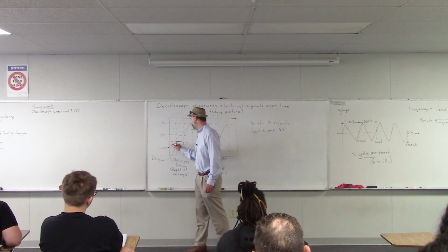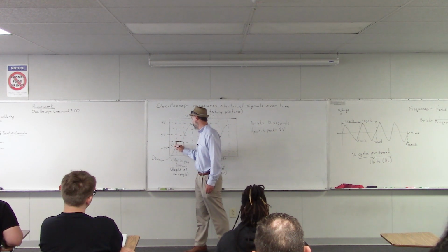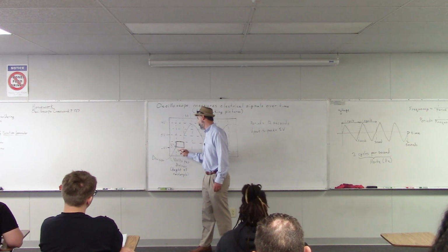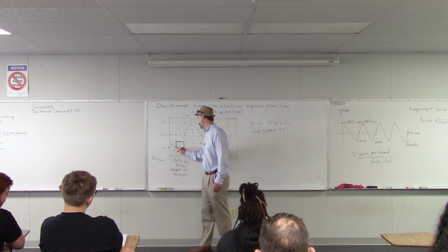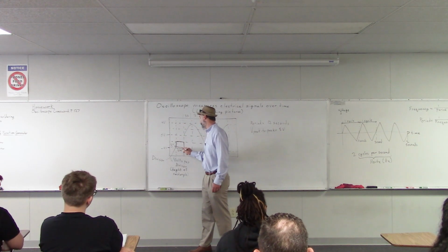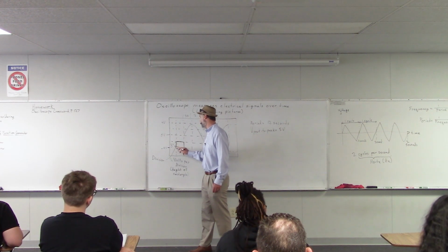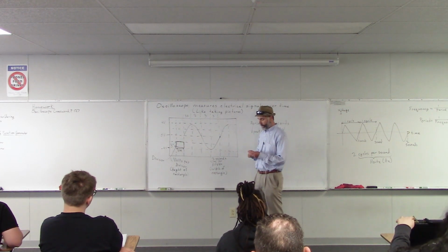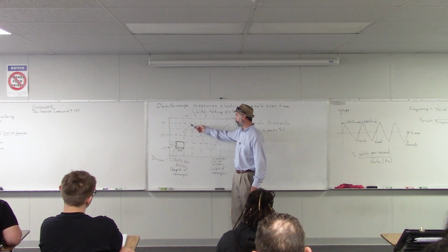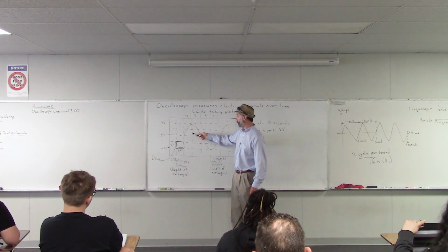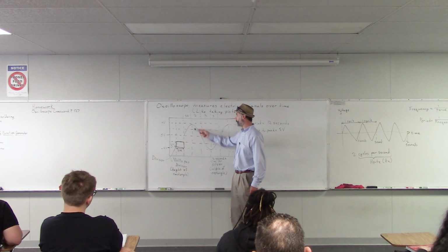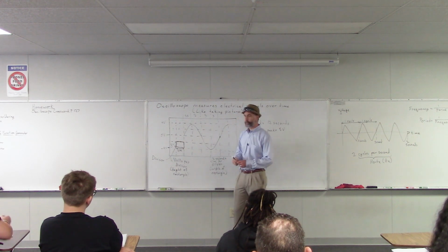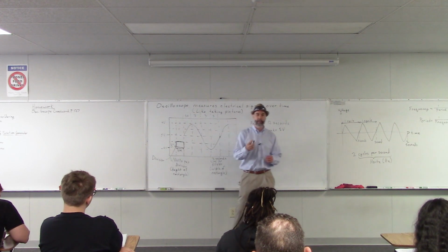So this distance there would be 2 volts from the top to the bottom, and 3 seconds from side to side here. So that's what each of these little rectangles represents: 2 volts high and 3 seconds wide. Then to find the size of our wave, or the amplitude, we count how many of these little rectangles there are from the very top to the very bottom. In this case, there are 4 rectangles from the top to the bottom, or as close as I could draw it.